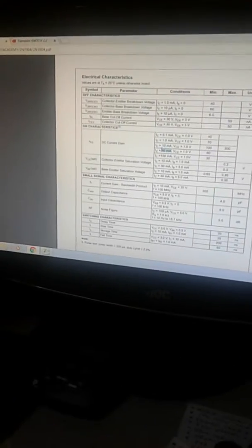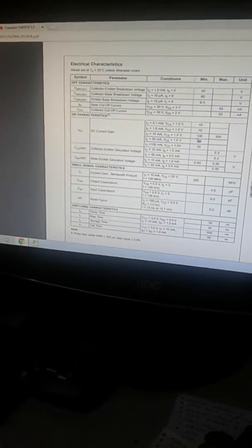Find resistor 2 here, the base resistance, to limit the current in the transistor to operate in saturation mode. So transistor magic formula, IB is equal to IC over HFE. HFE here is 60 from the table. Since we're operating at 20 milliamps, the HFE is 60. The collector current is the current flowing here to saturate the transistor. 0.02 divided by 60 is now equal to 0.0033 ampere.